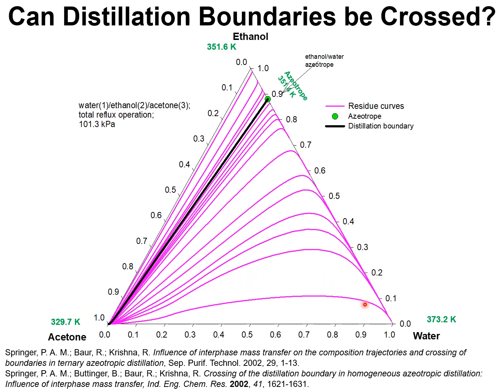These pink lines are called residue curves, and they map out the distillation trajectories that the compositions in a distillation column must follow, were the distillation column to operate under thermodynamic equilibrium conditions, in other words, following the theoretical plate concept of Sorel from more than 100 years ago.